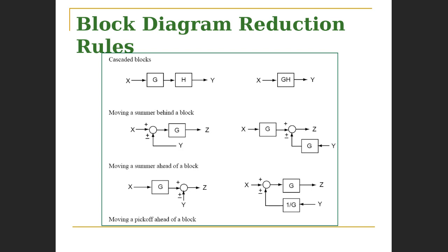So you notice in the first rule, which is the cascade block reduction, we have capital H, capital G, and these are representing Laplace functions for the different subunits. So there are 2 subunits in this block, and they're in series. Now, the signal that goes into this system is X, and the signal that leaves the system is Y.